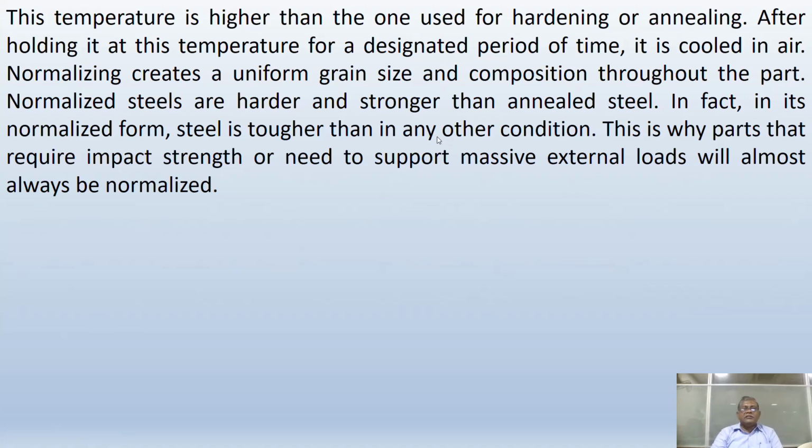This temperature is higher than the one used for hardening or annealing. After holding it at this temperature for a designated period of time, it is cooled in air. Normalizing creates uniform grain size and composition throughout the part. Normalized steels are harder and stronger than annealed steel.